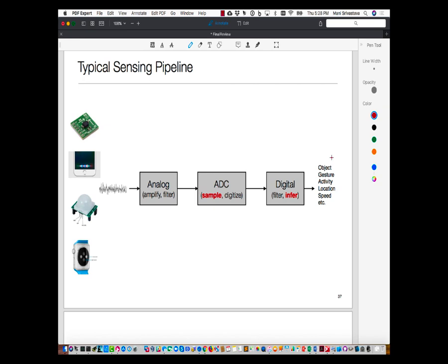I could potentially gain even more if I were to say my goal is not to reconstruct. My goal is to just estimate, let's say, the frequency, nothing else. Then maybe I could do even better. But in an ideal scenario, 3 points would have sufficed, except that those 3 points may not be nicely located. Maybe I was unlucky and they all sample at the same point. So you usually need to sample at more points to get an accurate estimate.